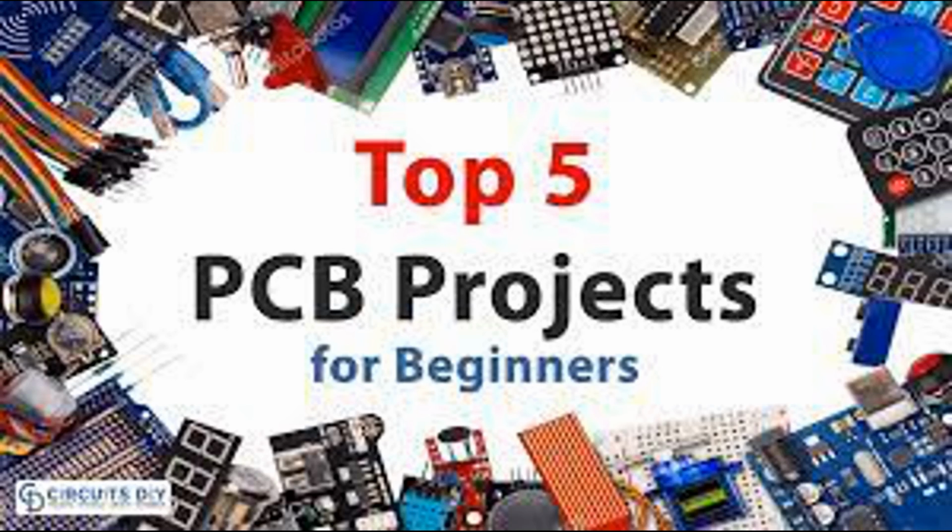Pads. Definition: pads, also known as solder pads or landing pads, are flat, typically circular or rectangular areas on the PCB surface. Pads are designed to provide a place for electronic components to be attached or soldered to the board. Function: pads serve as connection points between the electronic components and the PCB. Components like resistors, capacitors, integrated circuits, connectors, and other discrete devices are soldered onto these pads to establish electrical connections.